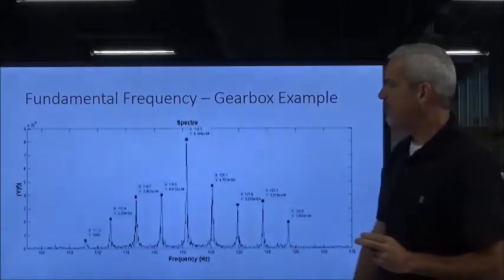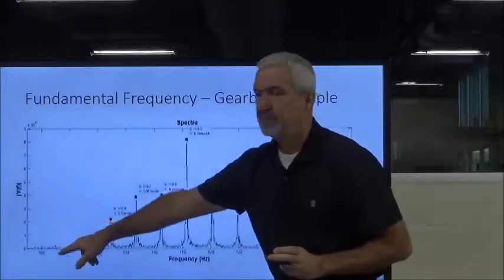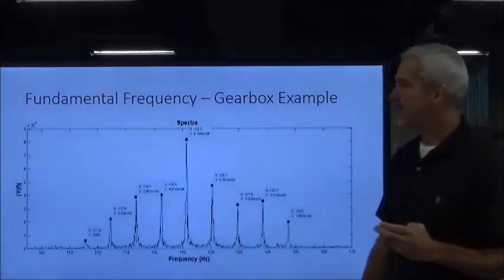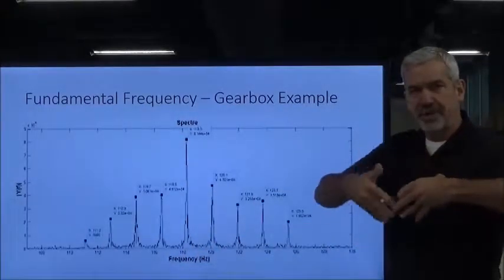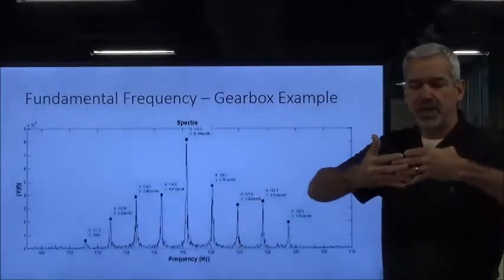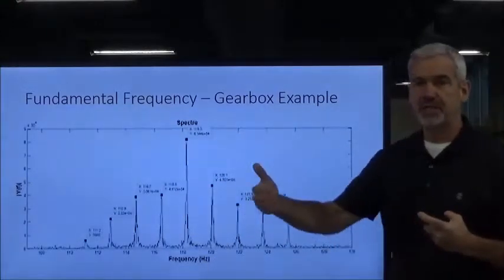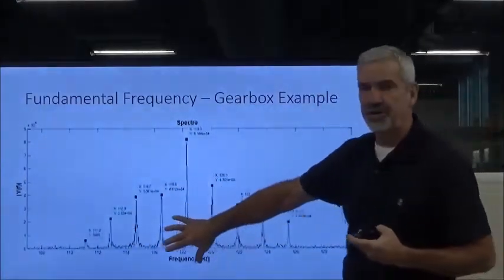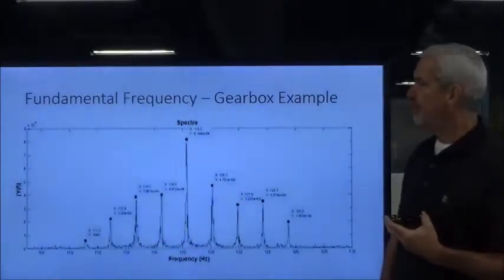So we wind up with our spectrum showing a much higher frequency than we did back at 900 when we just had a fan out of balance. Here we're looking at gear meshing, because there's a lot more teeth involved. Each time a gear meshes with another one, you've got multiple teeth on those gears, so your frequency is going to be greater. This starts to show up about right here in the 30 to 50,000 cycles per minute as far as gear meshing.